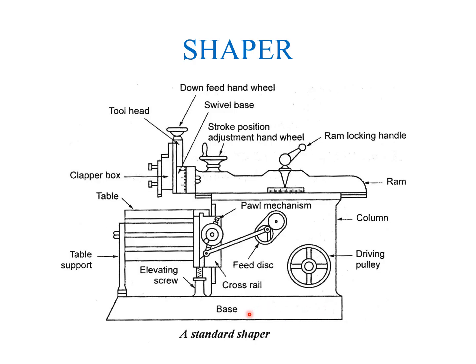Then ram. So this is the ram. It is the main part of the shaper machine. It holds the tool and provides the reciprocating motion to it. It is made of cast iron and moves over ways on the column. It is attached to a rocker arm which provides its motion in a crank driven machine, and if the machine is hydraulic driven it is attached to a hydraulic housing.